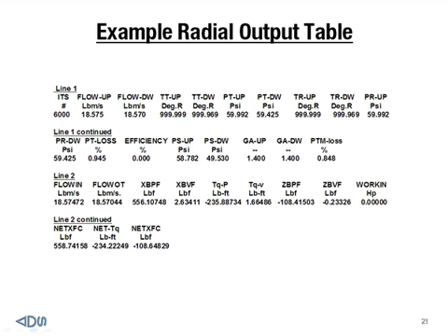So the next chart here provides this output table. I'm not going to go over the first line. That has pretty much been covered before and is very self-explanatory. But line 2 starts off with the flows. We've covered that before, but then moves on to the axial component of force on the airfoil, and this can be used to size attachments and forces on the airfoil due to shear, and there may be some reasons that the designer may be interested in that.